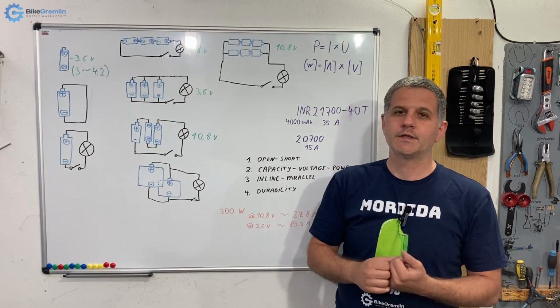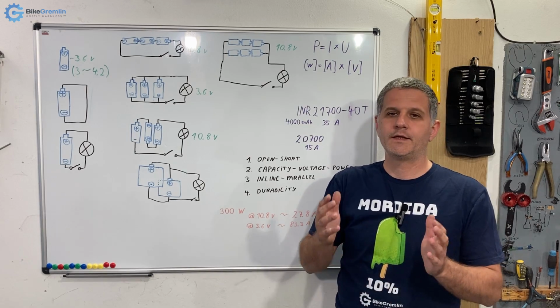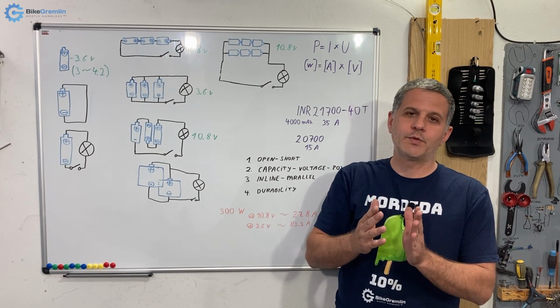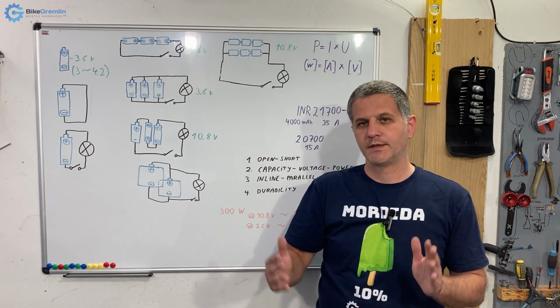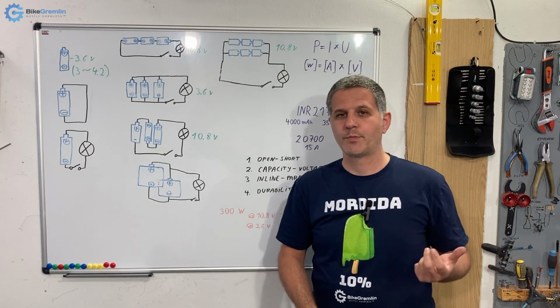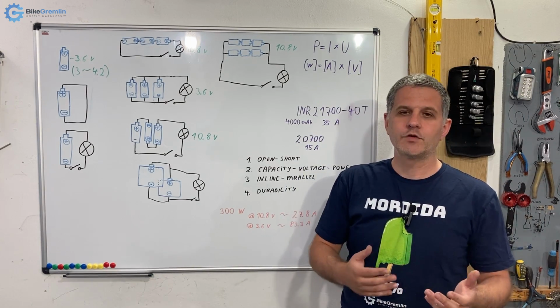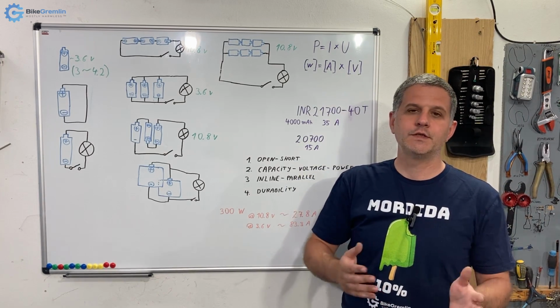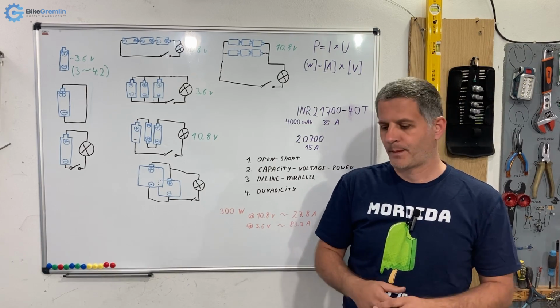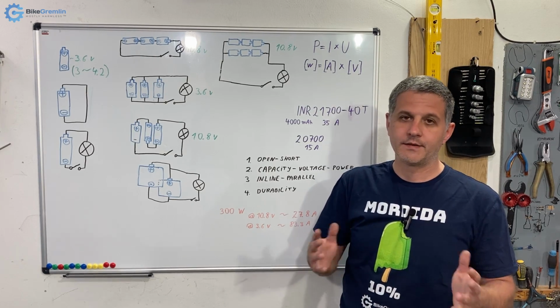So it is ideal to let them discharge to about 20% and recharge them to 80%. I understand that is not always practical, but when you have a choice, when it is convenient, it's better to go that way. And that's some rough guide.